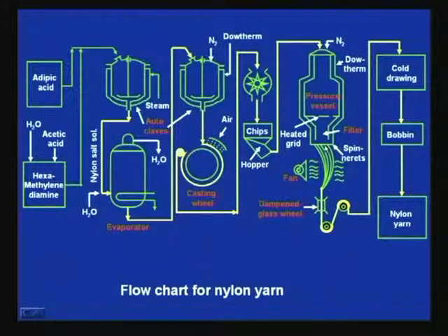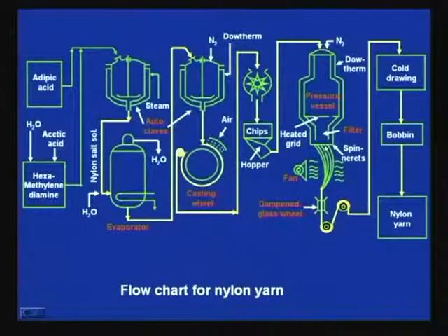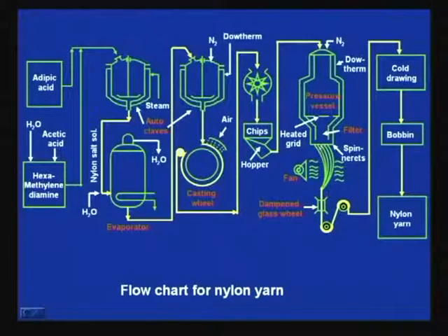Spinneret is a device which contains very narrow holes through which this molten mass, or sometimes in solution, is pressurized out, forming very thin fiber. So, thin fibers are coming out from the spinneret, that is cooled by fan, air blowing, and then these are